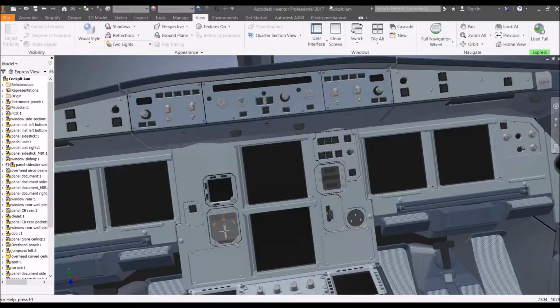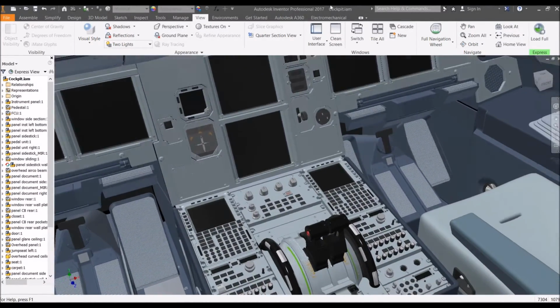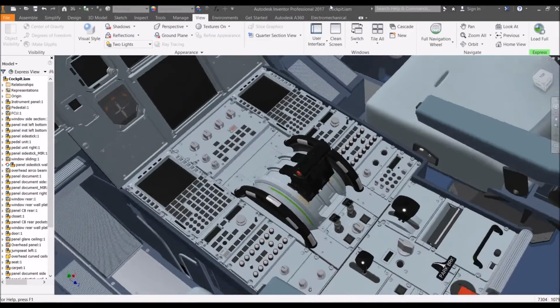Okay, so in order to delete all the surface detail, you want to copy the project, but not in a normal way, because if you copy the project by just copying the files in Windows Explorer, this is going to create problems because the assemblies are linked to file locations, and if you start modifying parts inside of an assembly, then you think you are modifying the file you are working with, but in fact you are modifying the original.